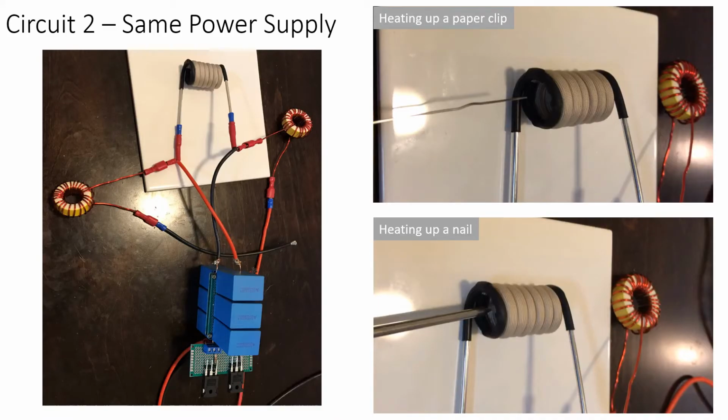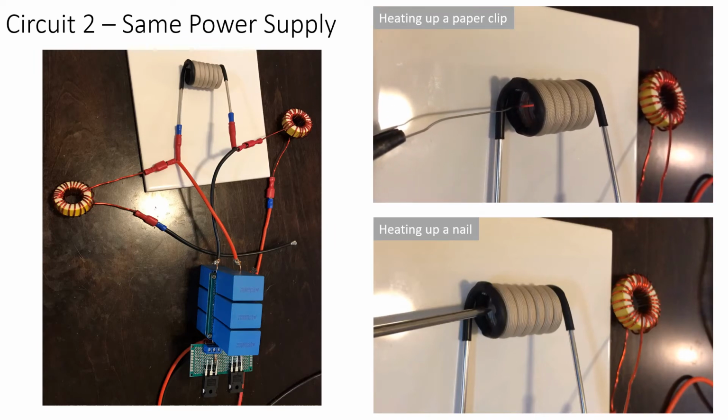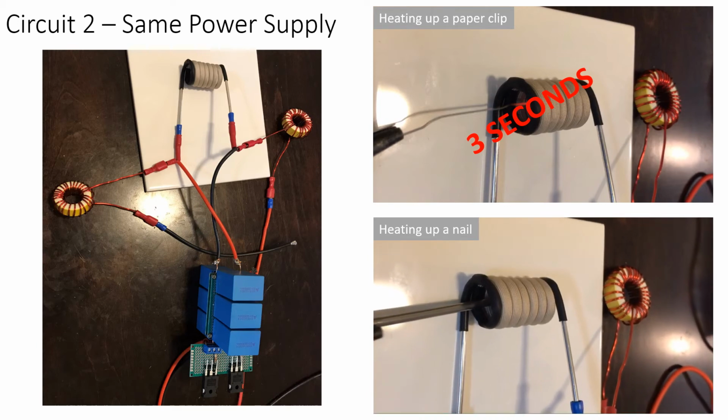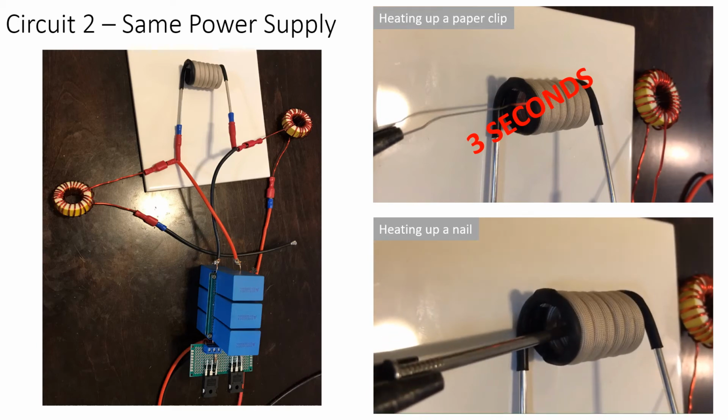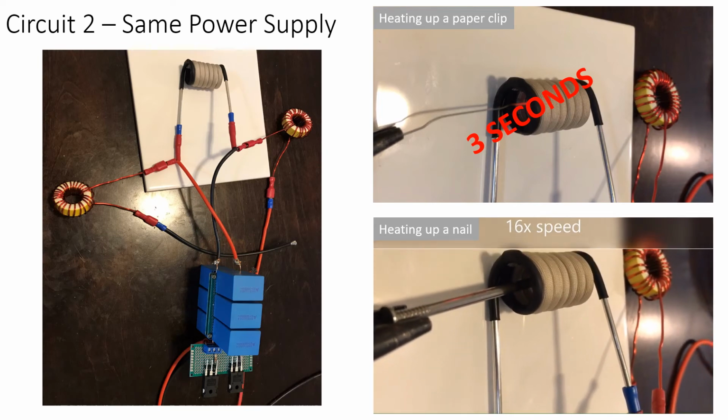Next, I used the improved circuit 2 to heat up an identical unfolded paperclip. The most significant change in this circuit was a larger capacitor array. When the circuit was connected without any object in the coil, the variable power supply was set to 10 volts and had a 5.1 amp current draw. When the paperclip was inserted, the current draw increased to 6.1 amps. This time the paperclip took only 3 seconds to heat to a red-hot glow, which is a 40% decrease in time. I then tried heating up a nail with this configuration. After waiting 91 seconds, it was hot but still not red hot, and I had to abort due to overheating of the circuit itself.